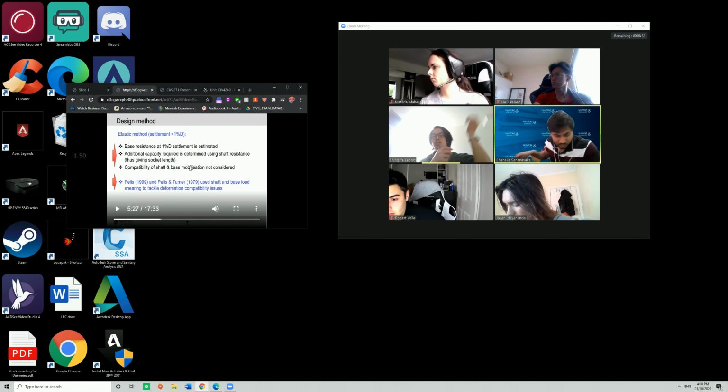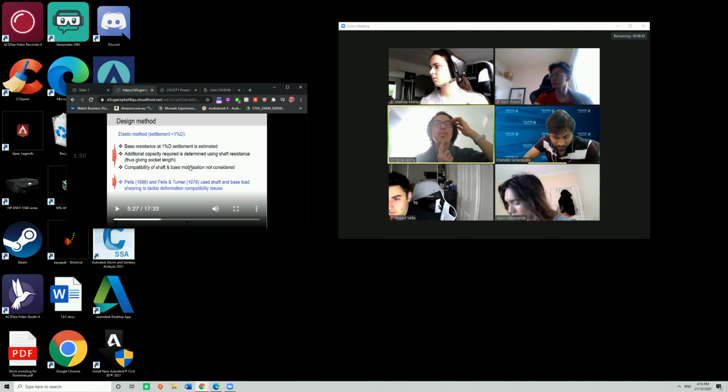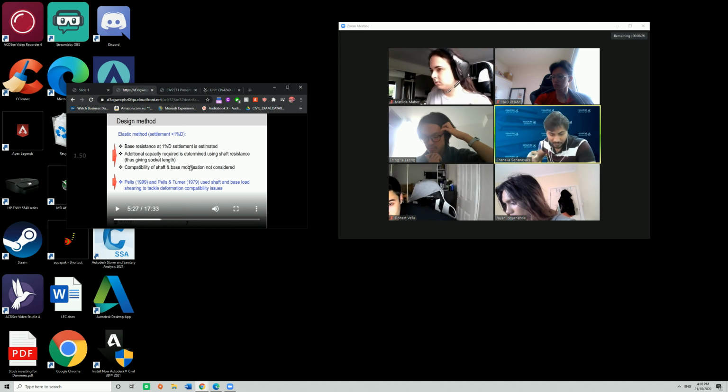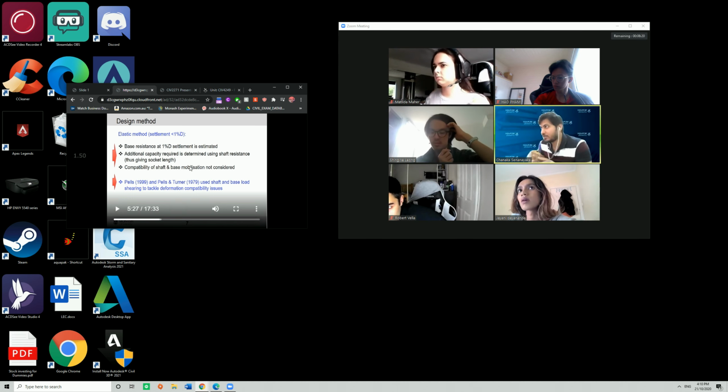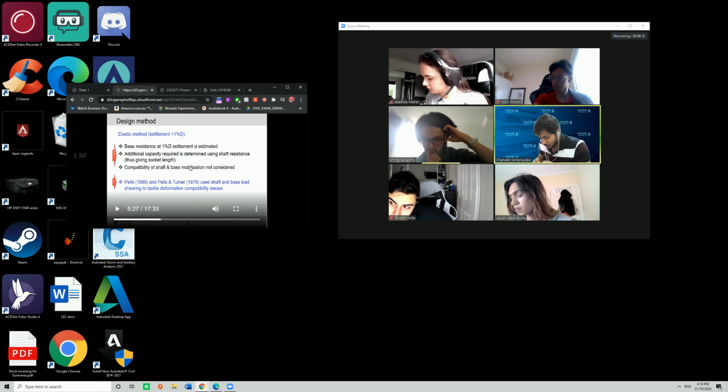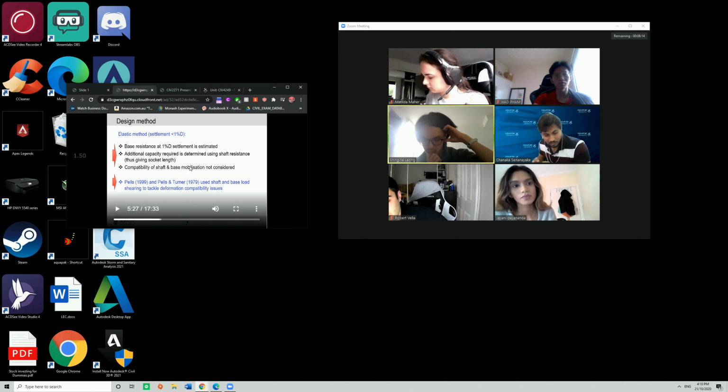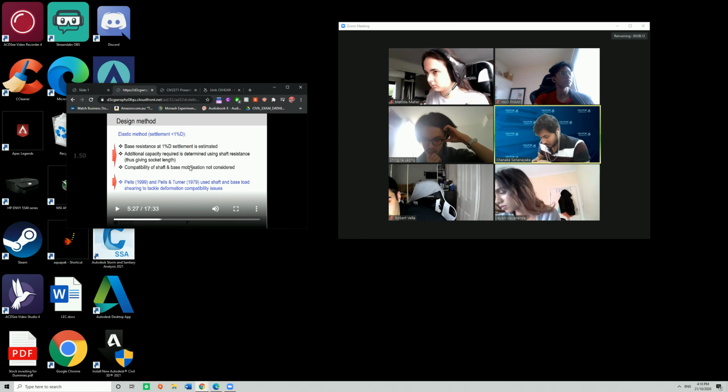11,059 kilonewtons. Okay. By assuming the 100% shaft, that means all the total load, all the ultimate load is taken by the shaft. I can find the initial length. Okay. 11,000